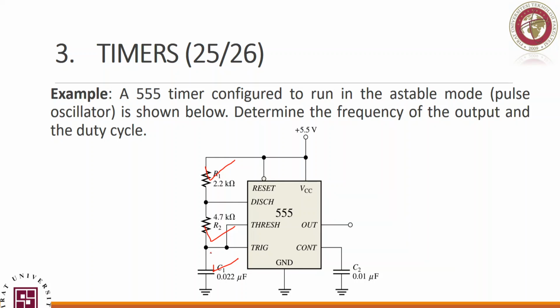If we have a level of charge more than 1/3, then here we will have an off state, and this off state will get C to start charging until 2/3 of VCC. When it charges to 2/3 VCC, the internal transistor will kick on again, and then we will start discharging until 1/3 VCC again, and so on.